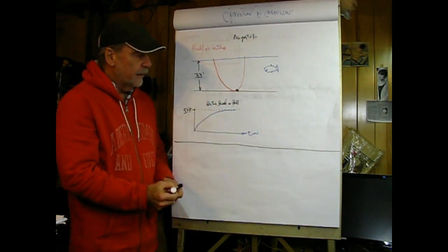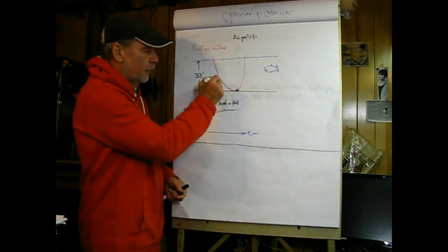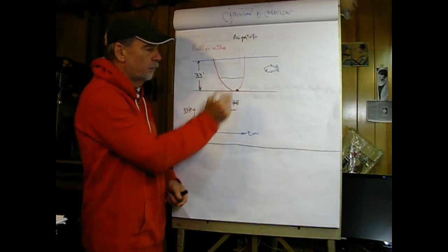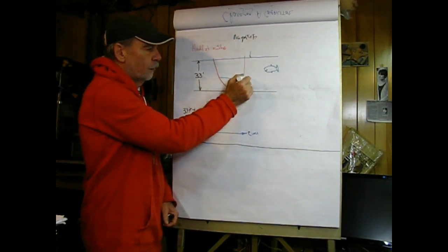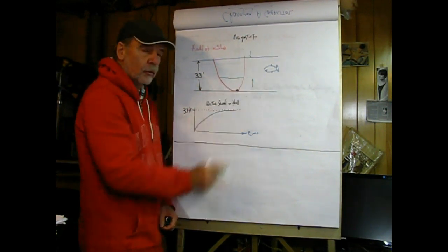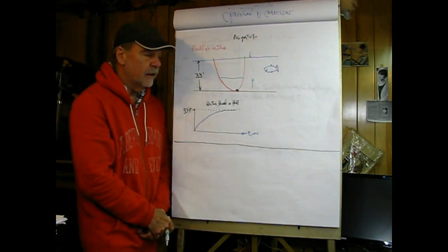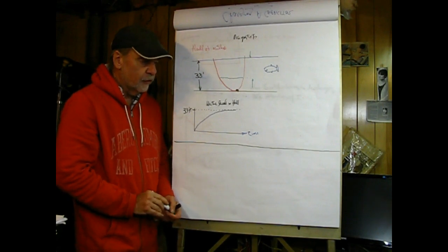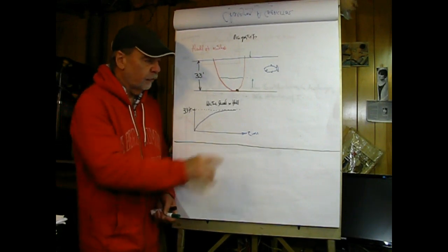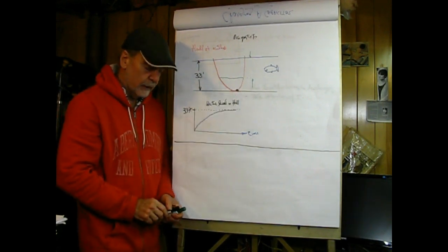As the water begins to flow in, the hull will start to fill up. At this point, the difference in pressure would be that of the surface versus that of the hull, which means that the pressure difference basically is decreased. So as it fills up, it'll begin to decrease, and what that means is that the flow rate into the hull is going to slow down.